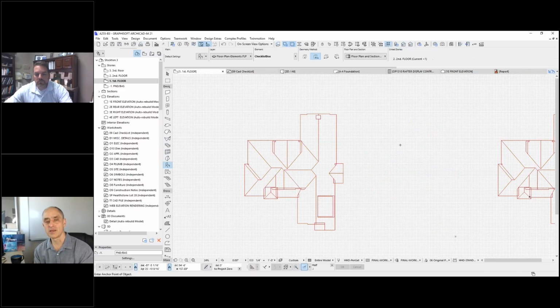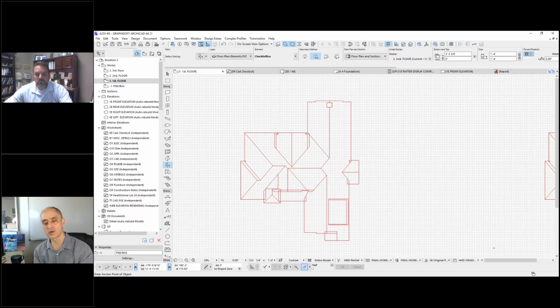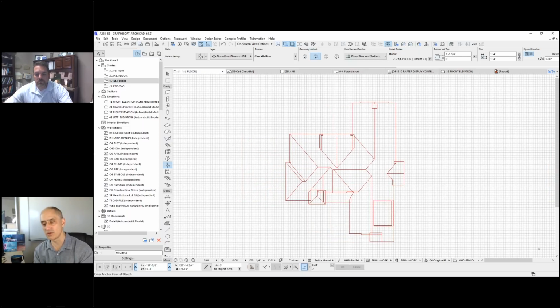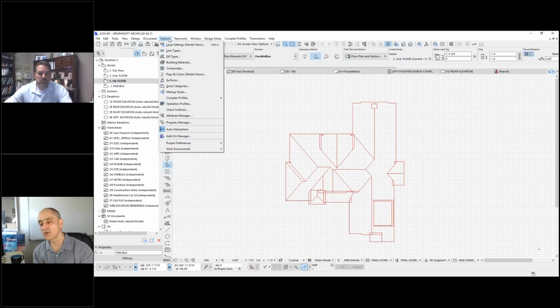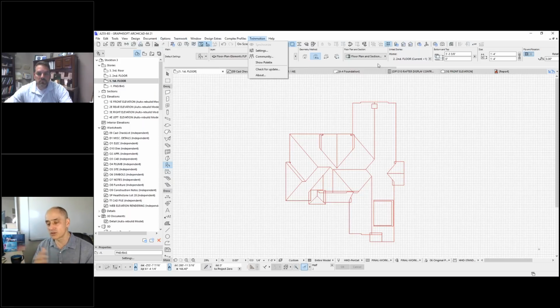And in the design menu, there's design extras, and then underneath there's roof wizard, or maybe it's roof extras or something like that, but it's under the design menu. You have to pre-select the roof elements before you do it. And then you can either say, hey, I would like to put just a series of rafters, or there are different sub items, or you can do the wizard, and the wizard basically has a whole